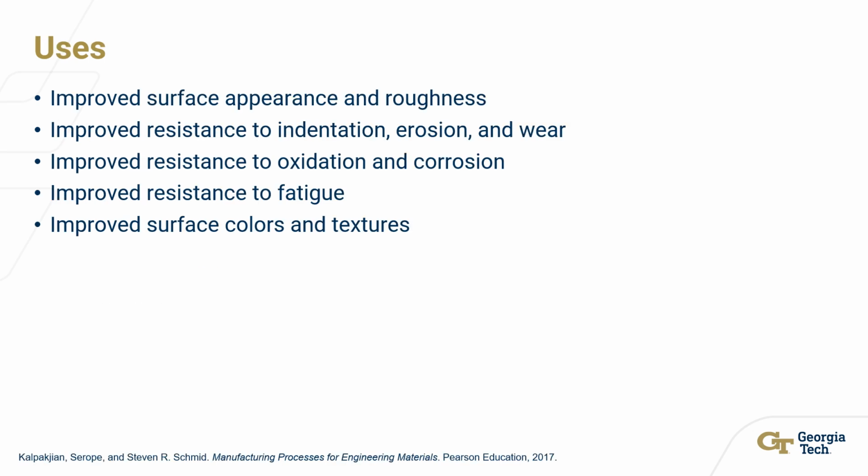Surface treatment methods are used in a wide variety of materials for several reasons. These reasons include improving surface appearance and roughness, improving a surface's resistance to indentation, erosion, and wear, improved resistance to oxidation and corrosion, improved resistance to fatigue, and improved surface colors and textures.